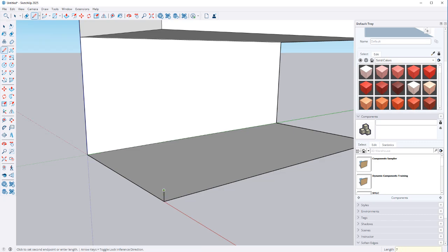That's the generic go-to that I use for a lot of things: they cannot be more than 7 inches of rise in each step, and they have to be at least 11 inches in run. You don't want your stairs to be, say, 8 inches tall because it's too high for some people to step, and you don't want them under 11 inches long because people might miss the step. So we'll do a generic 7-11 right now, and that gives us this little two-piece thing right here.